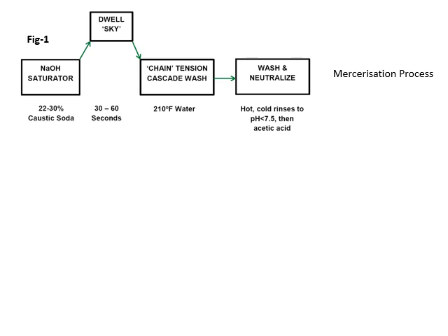Cascade rinsing is a counterflow washing process where the cleanest water is introduced through the last cascade unit. The water in this process is heated up to 98 to 99 degrees centigrade, we can say up to boiling, to remove the caustic soda. The first cascade washer uses the water which is most saturated with the caustic.